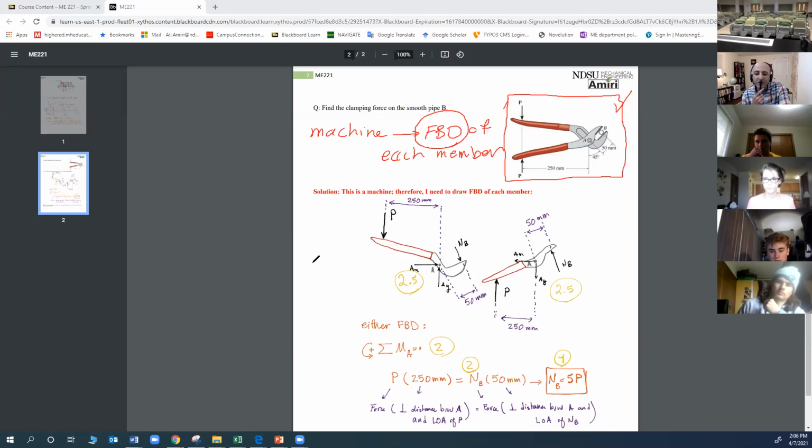I mean, this is a pretty important question, don't you think so? You're doing all this statics course and you're learning about free body diagrams. Shouldn't you know why we have to use free body diagrams? Don't you have to create two? Because if you tried solving it with the whole thing, everything will cancel out. Like your two P's would cancel out if you use the top figure. So there'd be no way to really solve for P then. Because if you tried using moment on A, the two P's would cancel out automatically. Same with the two normal forces on B. So you can't really solve for anything there.